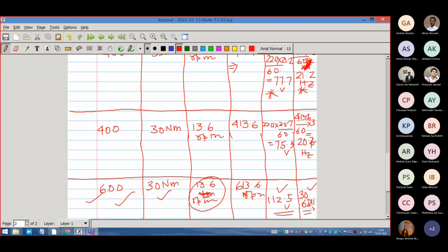So then it will develop a higher torque. So the machine will accelerate. The speed will go higher than 600. Then the error will be developed because the reference is 600 RPM. That is what is demanded. So the control system will develop an error, and that error will then produce a lower synchronous speed. We'll have to give a lower synchronous speed, and then that will be tried. And this way, the error will have to be brought down to 0, right?